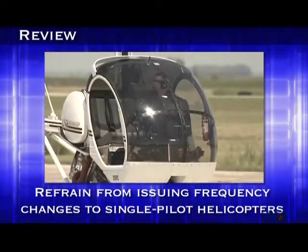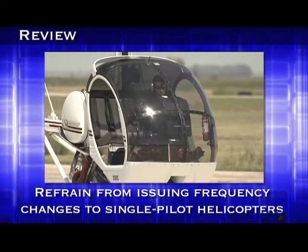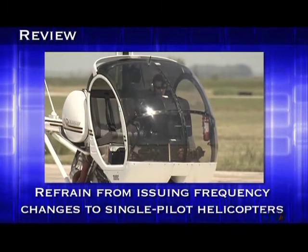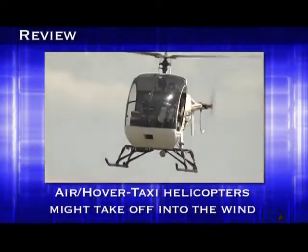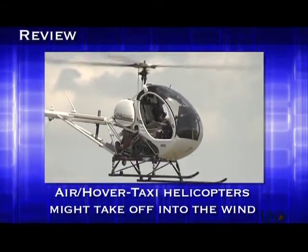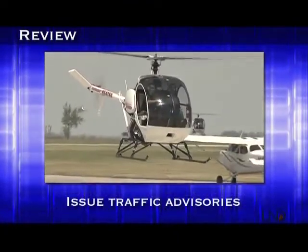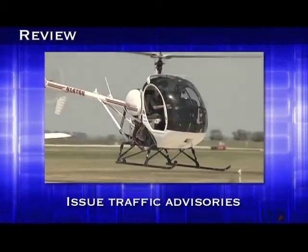If a helicopter is being operated by a single pilot, refrain from issuing frequency changes while it is operating near the ground, since hover operations require the use of both hands and both feet. Relay instructions from other controllers until the pilot can safely change frequencies. Like fixed-wing aircraft, helicopters need to take off into the wind and will do so to hover and air taxi. So they may start traveling in a different direction and then turn to follow your instructions. Be sure to issue traffic advisories to both helicopters and other aircraft so that everyone knows what's going on and what to expect. That's it for our series on ground control.